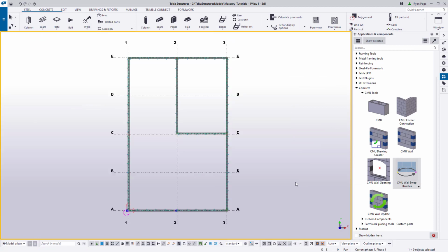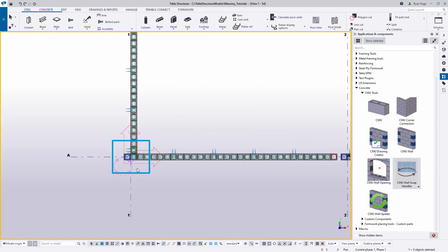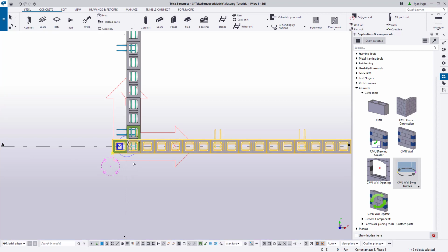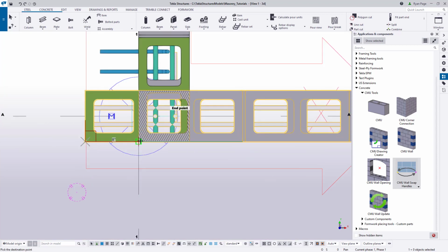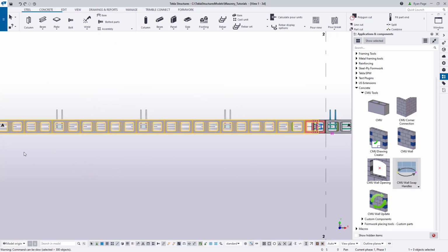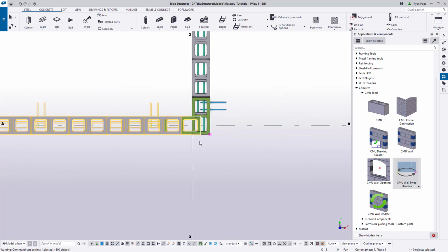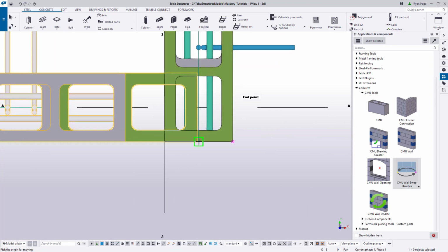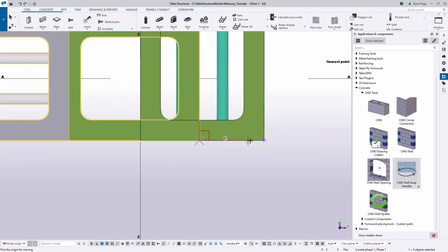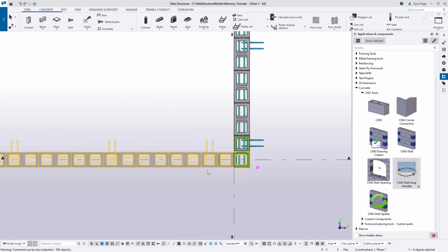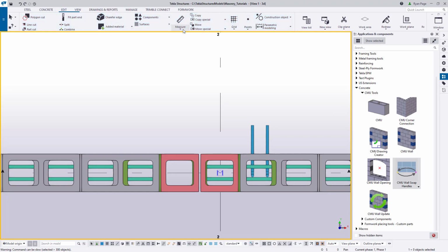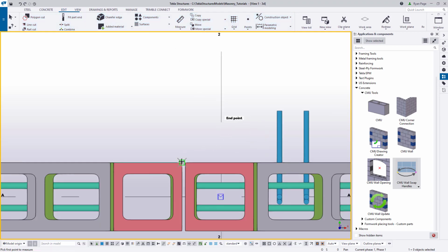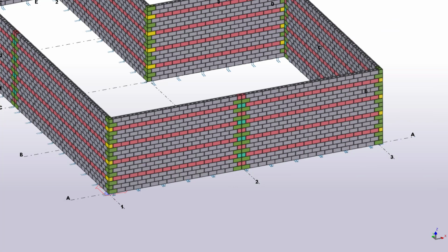You may also need to adjust the wall by selecting it, right-clicking, and then hitting Move to align the blocks to the correct position along grid lines A and 1 as well as A and 3. Make sure to verify you still have the correct thickness for your seam along grid line 2. When completed, your wall along A line should look similar to what is shown.